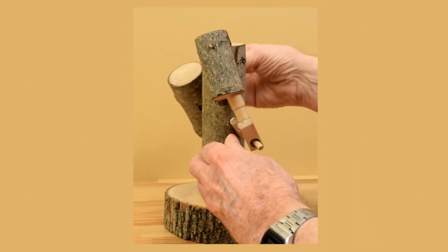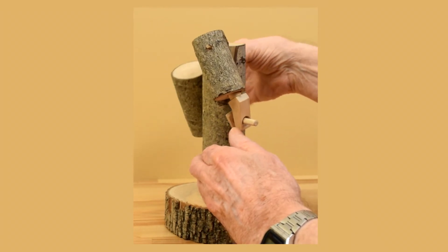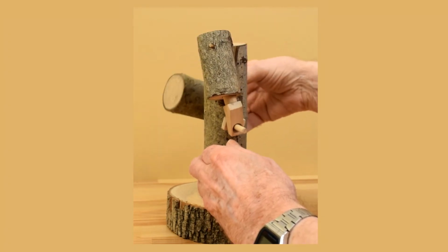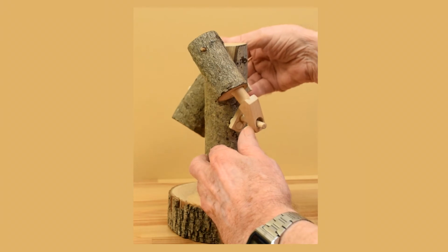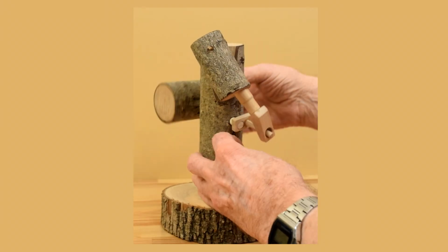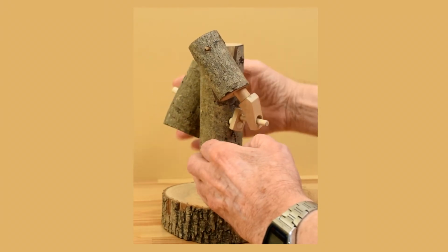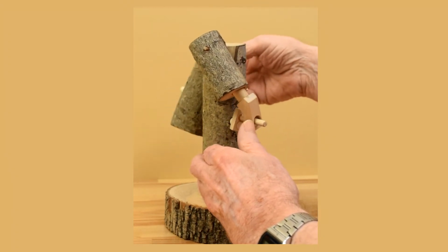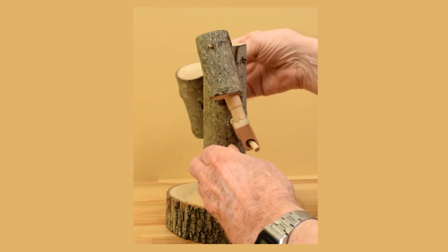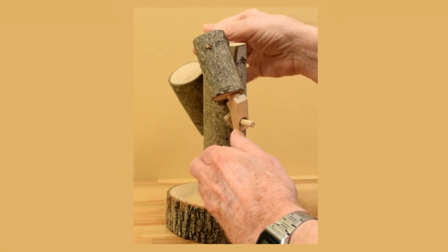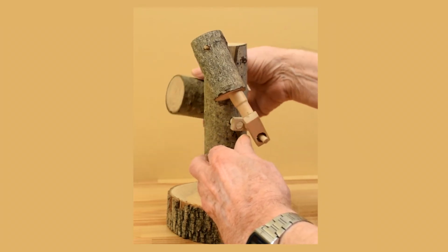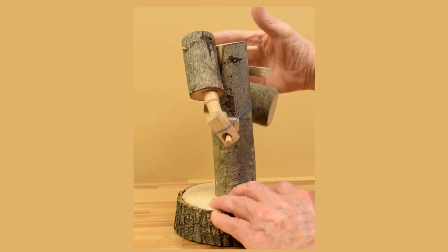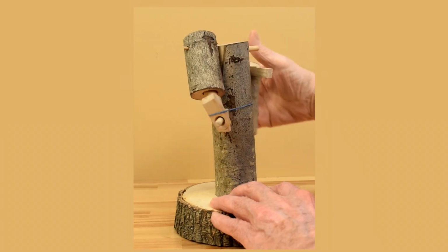always requiring some coaxing. It did seem that it took a bit more rotational assistance for clockwise rotation, as well as some coaxing in both axial directions. The mechanism just seemed to prefer counterclockwise rotation. Maybe this directional sensitivity isn't surprising, since the mechanism isn't symmetrical. I found that the mechanism was reasonably free with counterclockwise rotation and only an axial tweak toward the crank at the onset of the exhaust stroke. On a whim, I added a rubber band to provide this axial tweak.